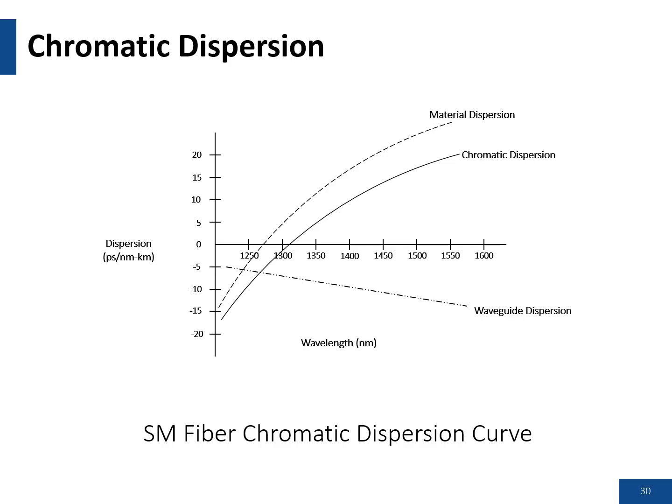This means there is more bandwidth capability at 1310 than at 1550. However, at 1550, the natural intrinsic loss of the fiber is lower than at 1310, so you can go further in terms of the amplitude of the pulse, but the pulse broadening is more sensitive at 1550.